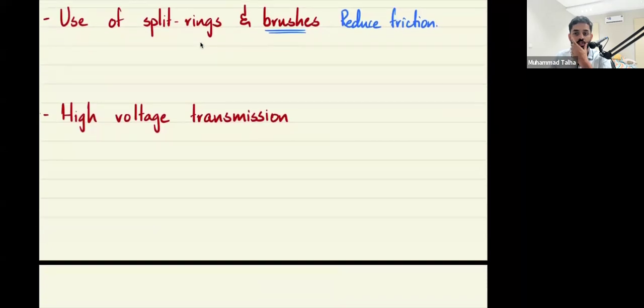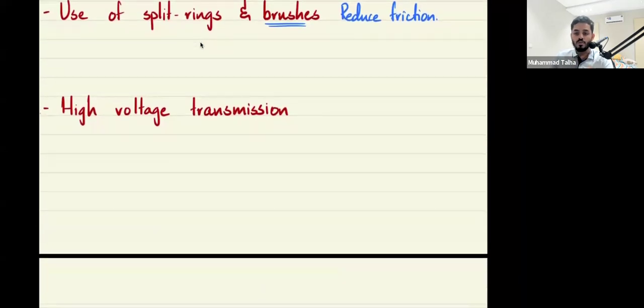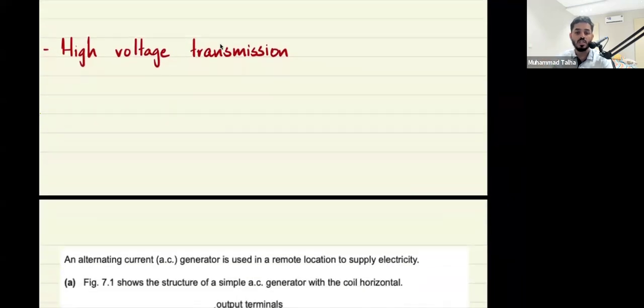High voltage transmission. So in terms of the formulas, and again, this is on my Insta, why high voltage transmission is what we use is because if we think about P equals VI, a higher voltage leads to a lower current, and by P equals I squared R that leads to less power losses.